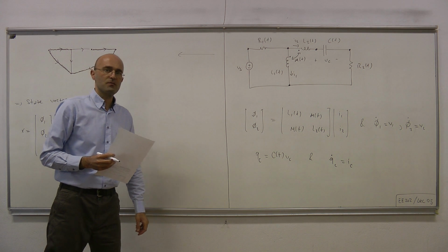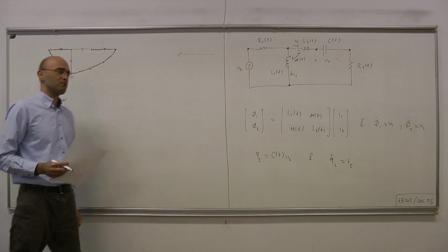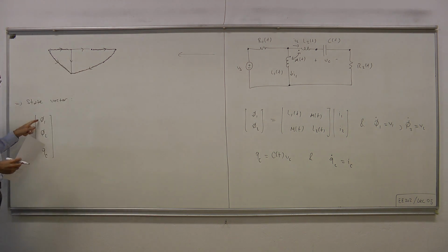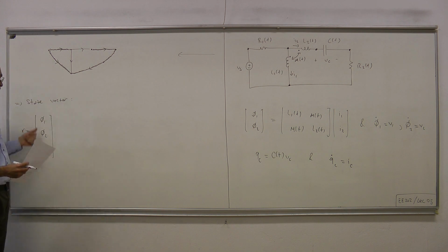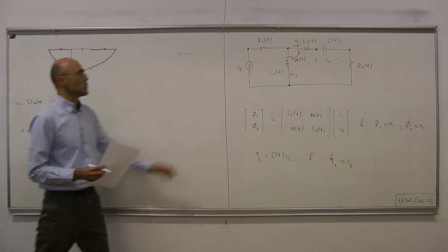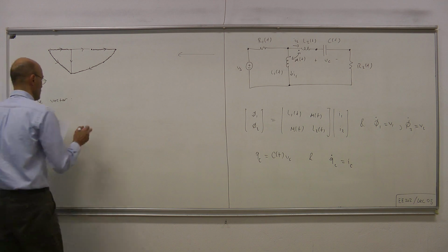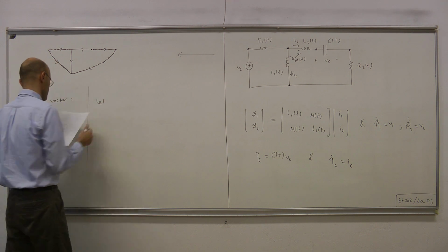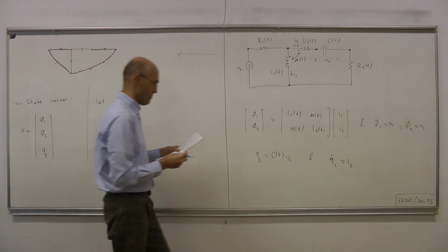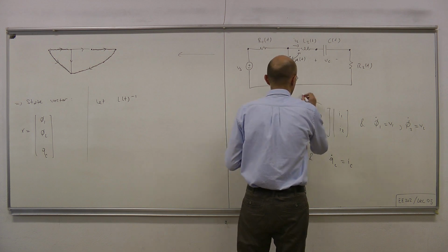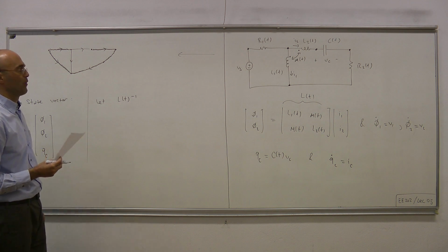of the capacitor. And now what we want to do is exactly what we wanted to do for the LTI case, that is obtain phi1 dot, phi2 dot, and Qc dot, okay, in terms of our formulation variables phi1, phi2, Qc, and also possibly the input Vs. Okay, so for that, let L(t), this is our inductance matrix, which is time varying for this circuit.